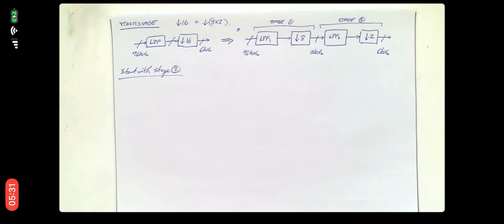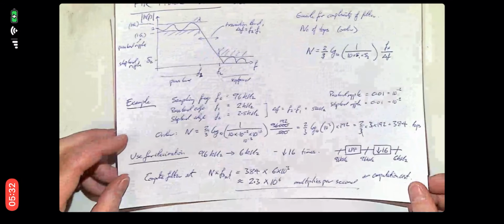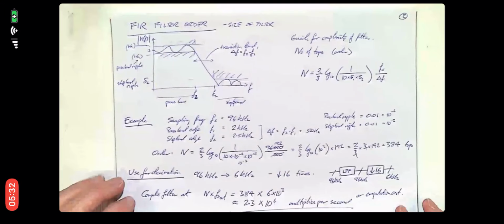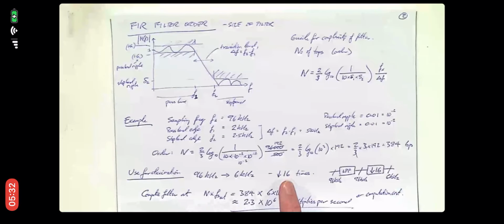Yes? This, the single stage one you did. Yes. What's the decimation amount, just arbitrary? So in the single stage 1 that we did here, the decimation amount was, we chose this decimation to be 16 times decimation here. What we probably should have done is to choose the decimation first and then choose a filter to fit that decimation. So this is just an example. We're using 16 times decimation as an example.